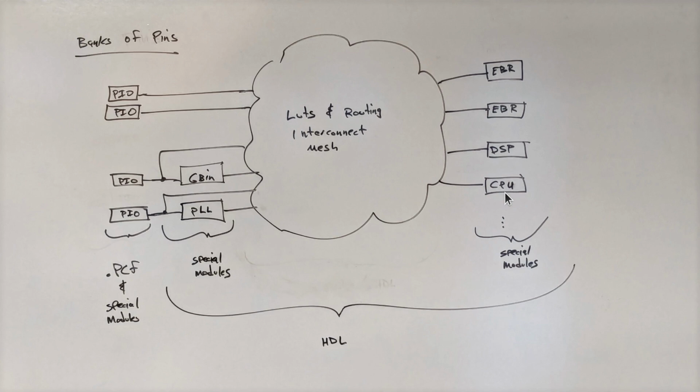Other common modules you could find in there, these are generally called hard IP, IP referring to intellectual property of the manufacturer. That's a common term that a lot of people use for these things. Other common ones will include Ethernet interfaces, SPI, I2C, serial UARTs and things like that. Okay, and of course that's why, other than the number of LUTs and the number of I/O pins and whether the LUTs are 4 in or 6 in or 3 input or whatever, those are the things that differentiate different FPGAs and different vendors, right? There's the total speed, total number of LUTs, how many inputs a LUT has, and what kind of hard IP does the FPGA have. So that there's your differentiation, okay?